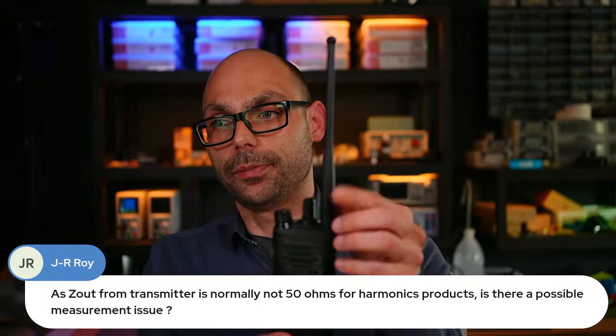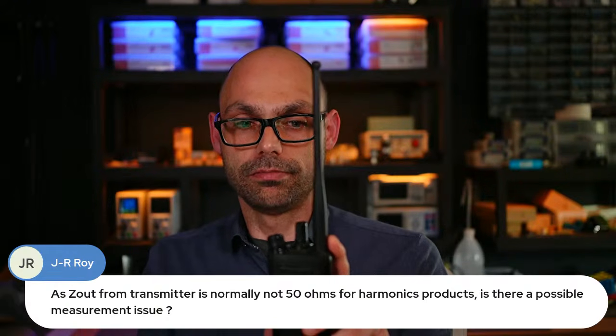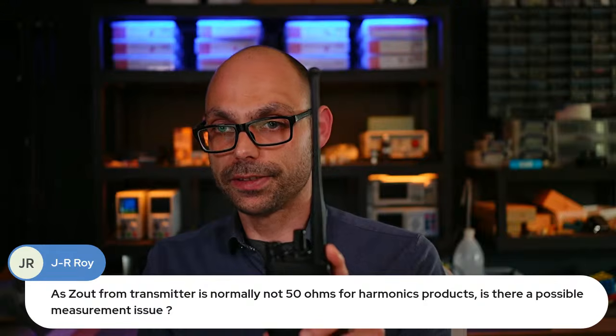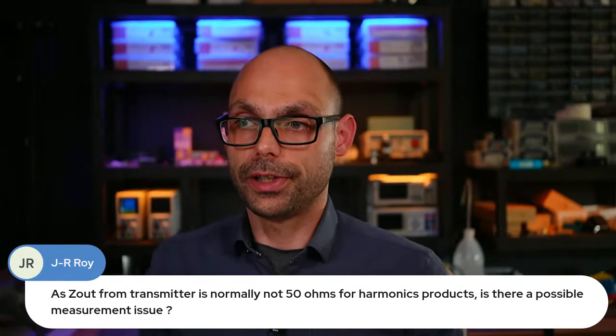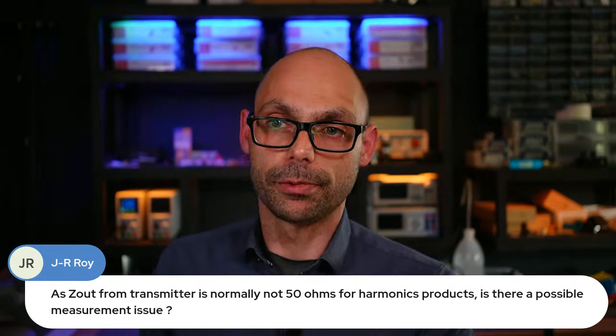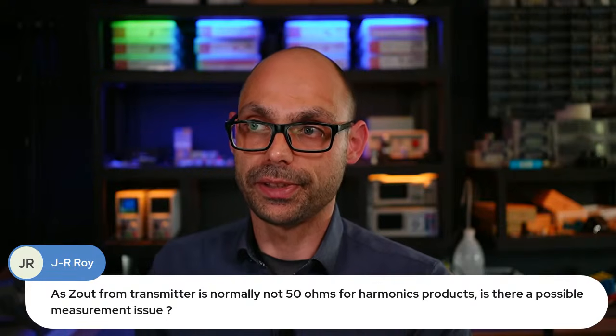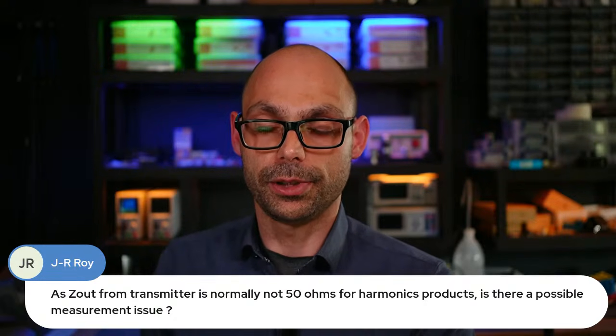Why? Because this antenna will not be a good antenna on all those harmonics, and therefore the real harmonic output will usually be lower than what you have in the conducted measurement, but the standard is actually not clear on what you do in that instance. It just dictates that, and technically, if you want to play lawyer, even if you have a transmitter that's designed for 75 ohm output impedance, for instance, I don't know why you would, the standard dictates to use a 50 ohm measurement antenna. I'm not sure why, but that's how it is.